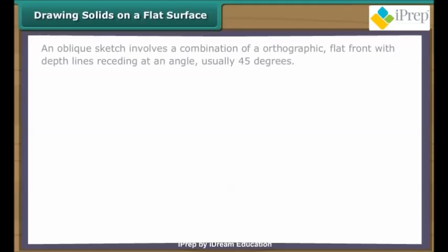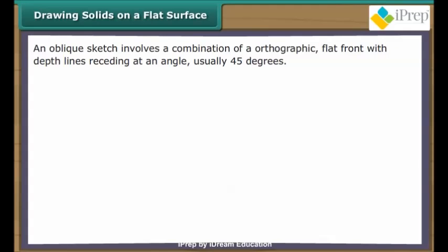Drawing solids on a flat surface. Let's learn about oblique sketches. An oblique sketch involves a combination of an orthographic flat front with depth lines receding at an angle, usually 45 degrees. Let's draw an oblique sketch of a cube.